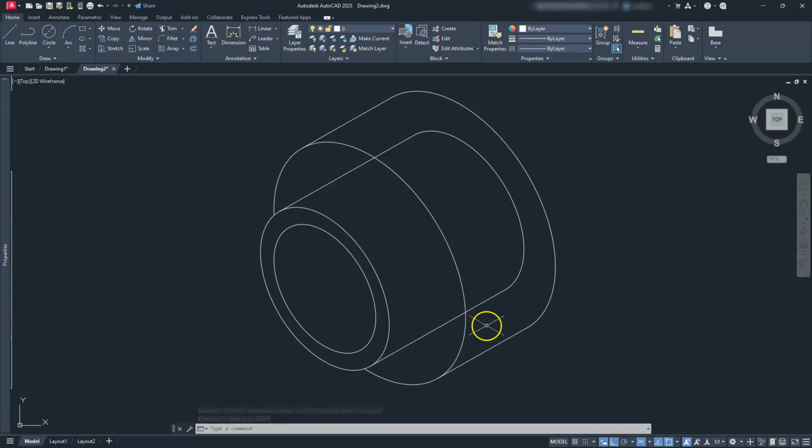Now we have a kind of setback that's happening right at this location. All right, so we have an ellipse there, and I'm going to see what the number of it is. Let's see, so we have our 43, we have our 34, and then we have our 55. Okay, that's what I'm looking for. So I'm going to switch to an isometric left, EL, enter. I'm going to go to this center, which is located here.